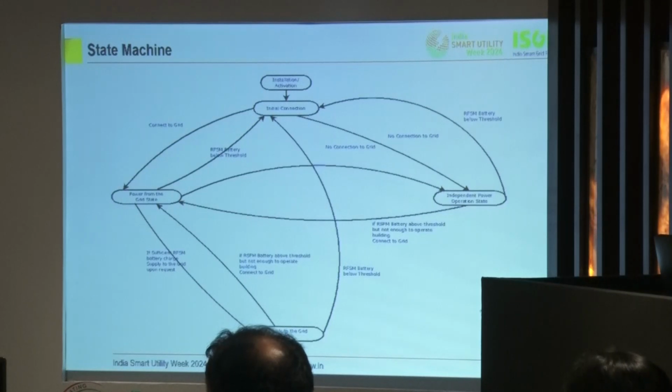That's the grid integration. And once the grid is charged, or you have a completely charged rooftop module, you can say, okay, grid, I don't want your supply for now. I can use my own supply for the moment. Actually, the building control unit or building control system will compute how much of its own power it can use. It's dynamic, not certain. It depends on how much the battery charge is and what is all connected at the consumer end for the building. It's not hard and fast that way.